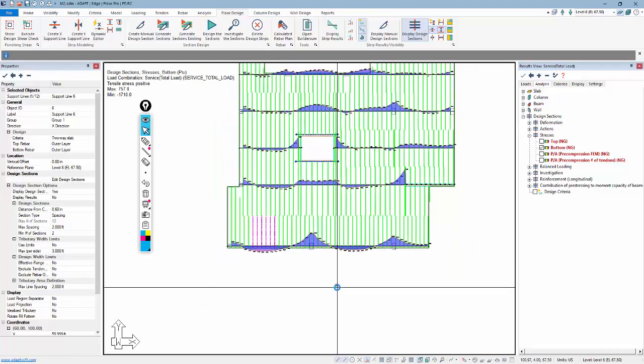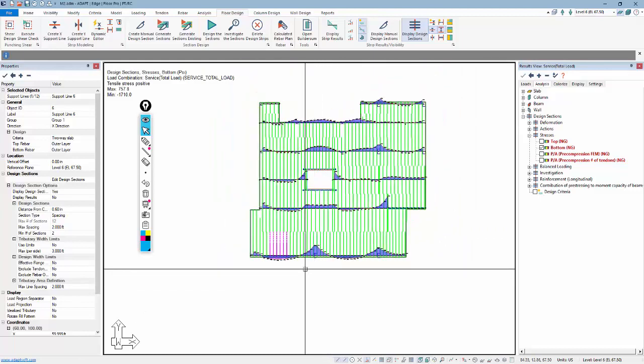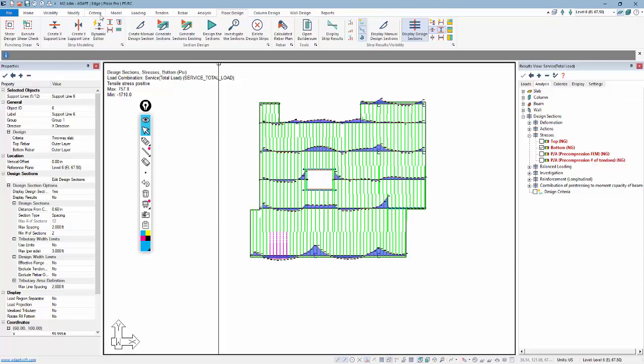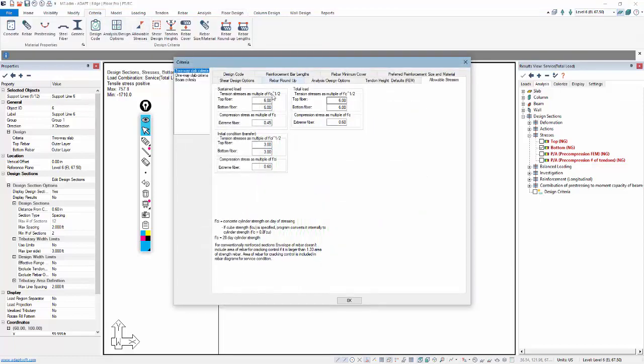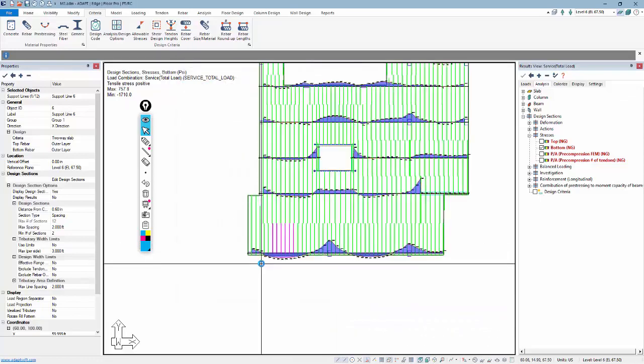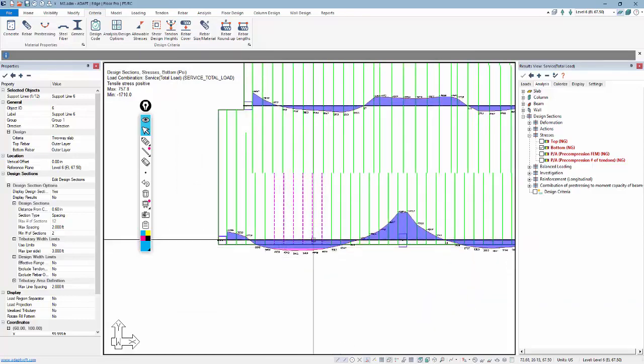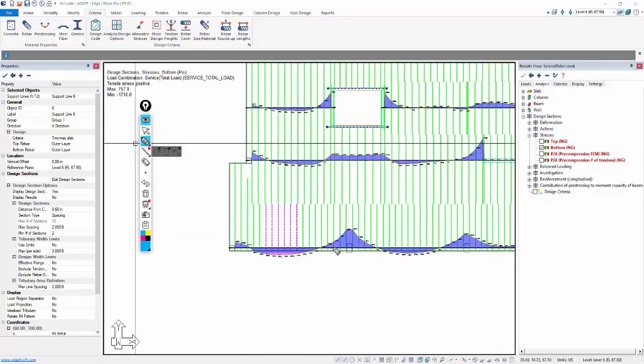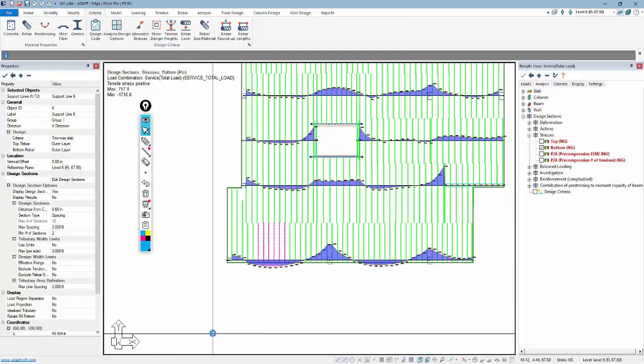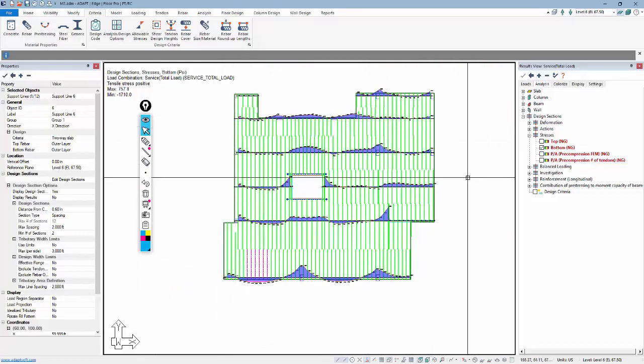Bottom stress, for example, we have a few regions here where our stresses exceed allowable. The allowable stresses are set under the criteria, and this is set to 6 square root of f'c for a two-way slab. We have other settings for one-way slabs and beams, but you can see this is exceeding that allowable value. So this is an area where we may have to add, this is a uniform cable, we might have to add tendons here, pull those out in this direction in order to take care of that stress for that one region. In other regions, here I'm just assuming that the pre-compression is working.